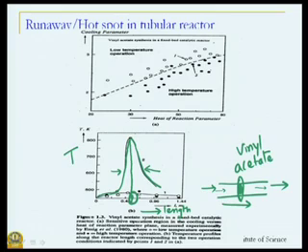It is a matter of little consequence that these temperatures also come down. Now, why do they come down here? They come down here because this was a controlled experiment. They come down because by the time temperature reaches such a high value, your reactant is almost completely exhausted, and therefore, you have the reaction almost stopping instantaneously. So, no heat generation anymore, and you have a complete meltdown.